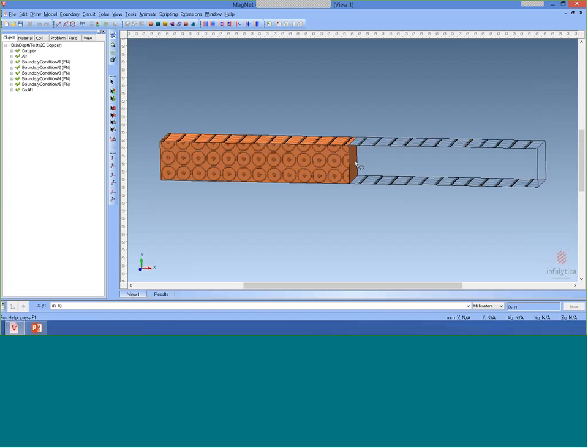It's a current carrying block of copper, and we will look at the results of this at a specific frequency. Because the field is normal at this boundary, essentially we created a set of images that goes from the top of the slab all the way up to infinity, and the same holds at the bottom here. So this is essentially the equivalent of the analytic version of the skin depth, where we'll be calculating an infinite slab with a field that is going to be parallel to that face.